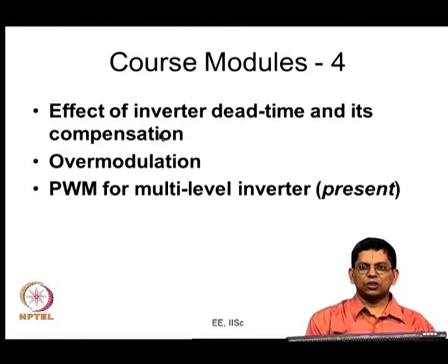So, this is a certain kind of non-linearity coming up there, that is you are modulating at a particular modulation index, you are producing an output, and that output is slightly different from what you want, plus there are also low frequency distortions getting introduced in that. Your modulation frequency may be 40 hertz or 50 hertz, let us say 50 hertz. This also introduces low frequency distortions like 250 hertz or 350 hertz in the inverter output.